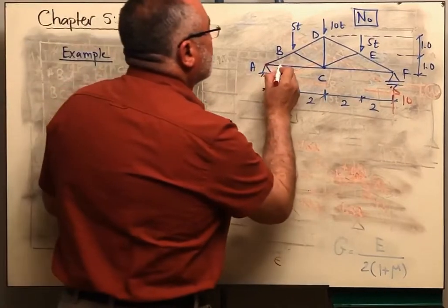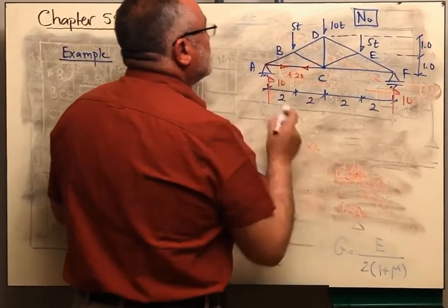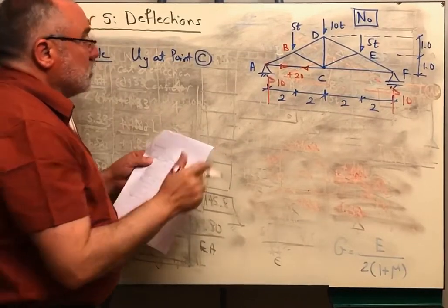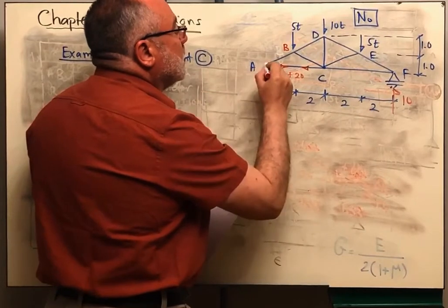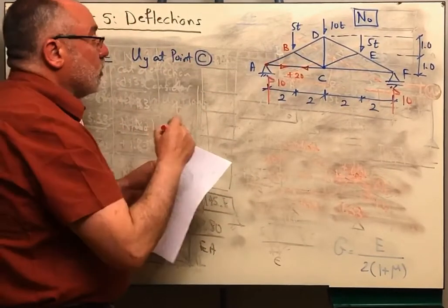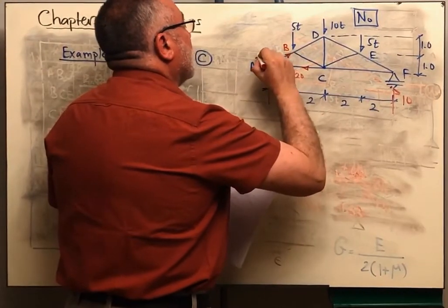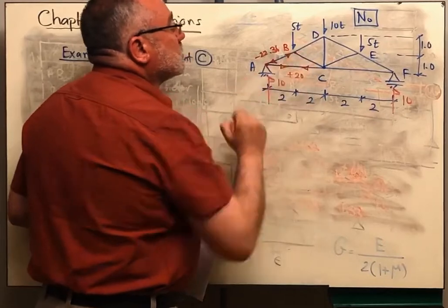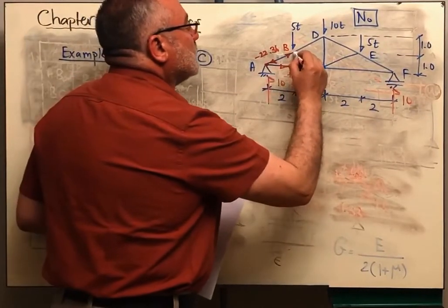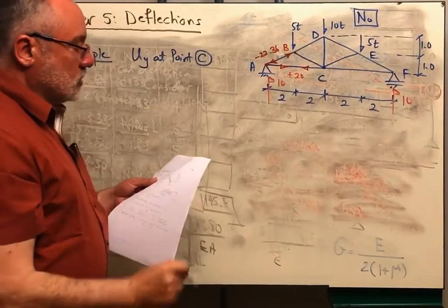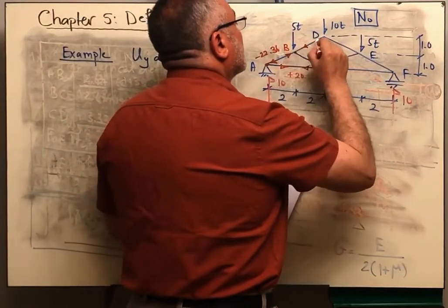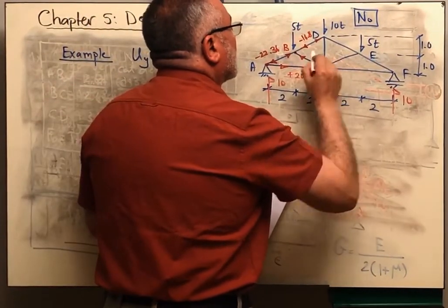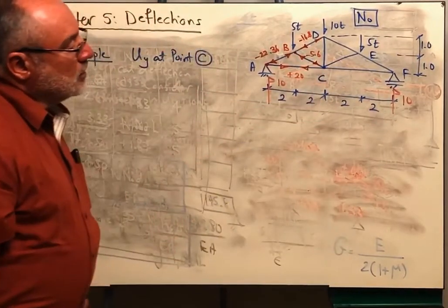So if you did this, you will have a positive force here of positive 20, and you can solve for the force here by taking equilibrium of forces at point A. You can determine the force in the member AB from sigma Fy is equal to 0. So here you are going to have compression, and it is negative 22.36. Now you are having a joint where you are having 2 unknown forces. So I can determine the force in member BD and BC by solving 2 equations in 2 unknowns. You can get this one. It will be negative 16.8, and here it is negative 5.6.